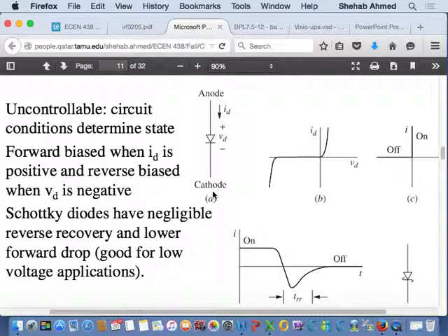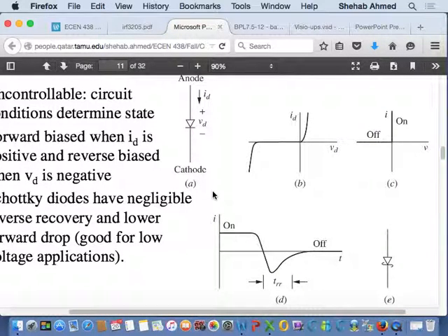This conversion from conducting state to blocking state, the physics is what happened in 370, right? Depletion layer, electrons moving to the other side. That's when you have a gap, for example, in the silicon layers of the diode, and when the diode would like to conduct, electrons move across the depletion layer so that you create current moving, right? And then when the diode starts to block, what happens? This depletion layer, you have to build it up again.